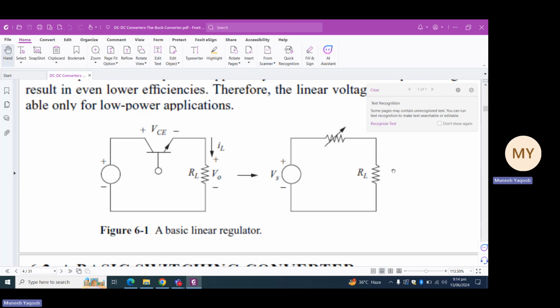This scheme can be performed using a BJT. In the figure on the left hand side, you can see that we can use this bipolar junction transistor as an amplifier in its linear amplification region. If we use that amplifier in the linear amplification region, we will consume 8 volts in this amplifier and hence we can get 4 volts across the load resistor RL.